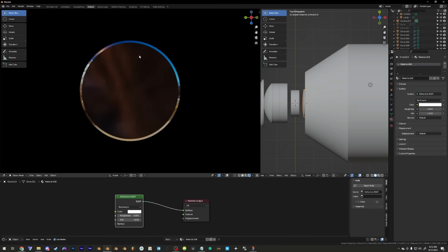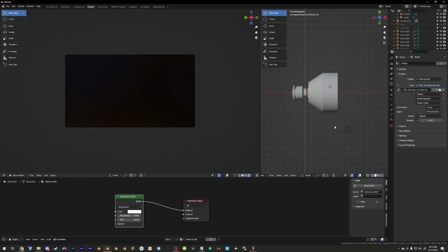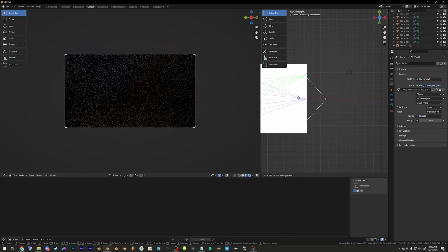see it's focusing perfectly to a point. That is what we want to see. If we want to analyze the image even more clearly, we can change our interpolation mode from linear to closest. This gives us a pixelated grid for us to follow, and now we can see a very, very clearly focused image. Let us go back to our camera, and let us move our sensor and line it up with our diagram right here.